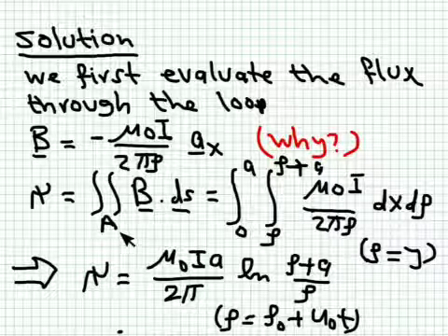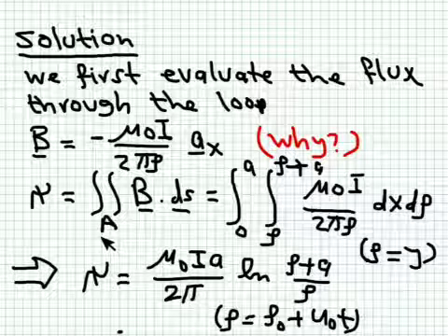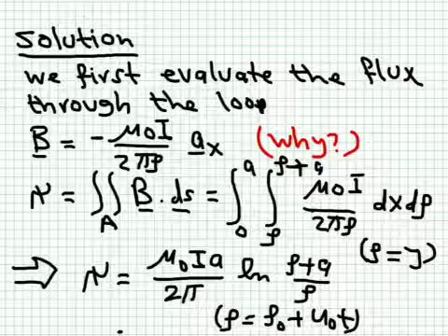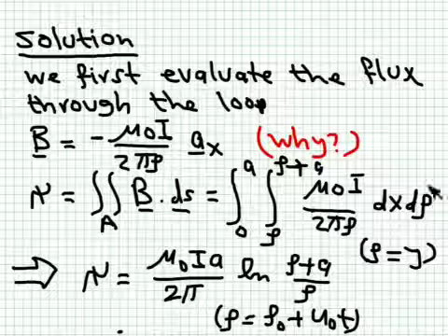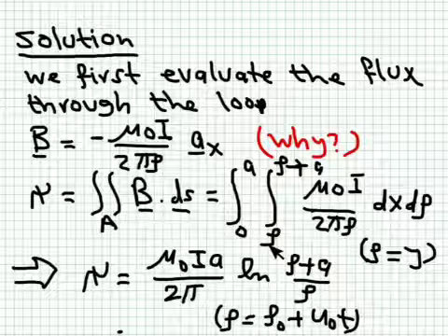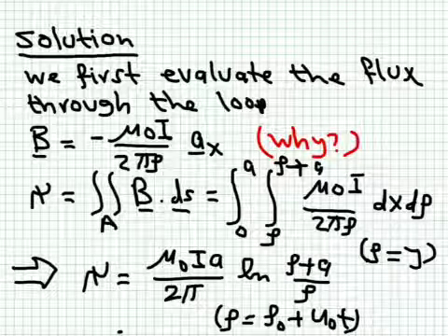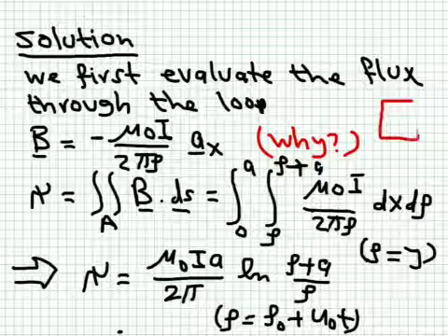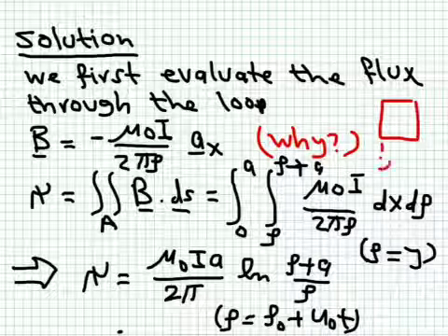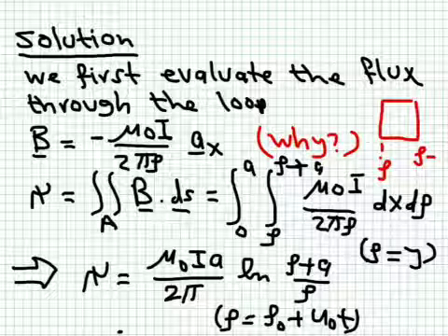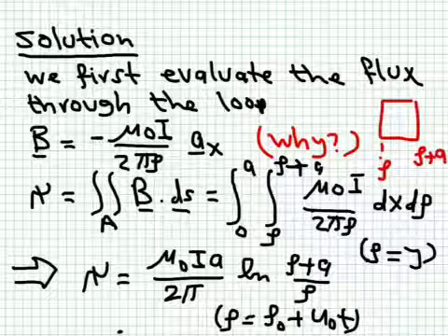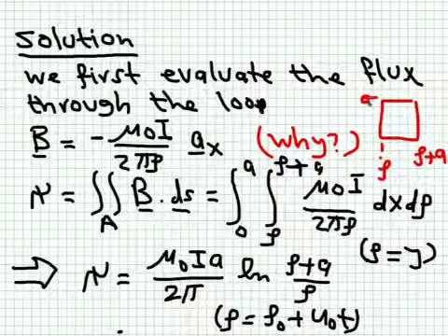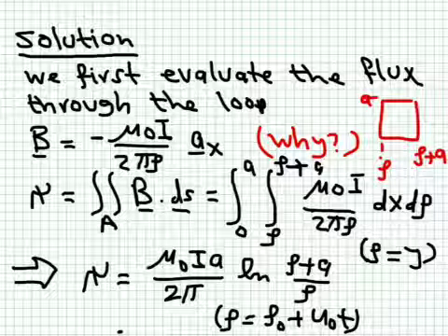The expression for the flux is simply to integrate over the area of the loop of B dot ds. So we integrate over rho, where the variable rho changes from a certain rho to rho plus a. Remember, when you integrate over the coil, this is how your coil looks. At any time instant, it starts with rho and ends with rho plus a, even though rho is a function of time. And the other dimension is not changing, you integrate it from 0 up to a.